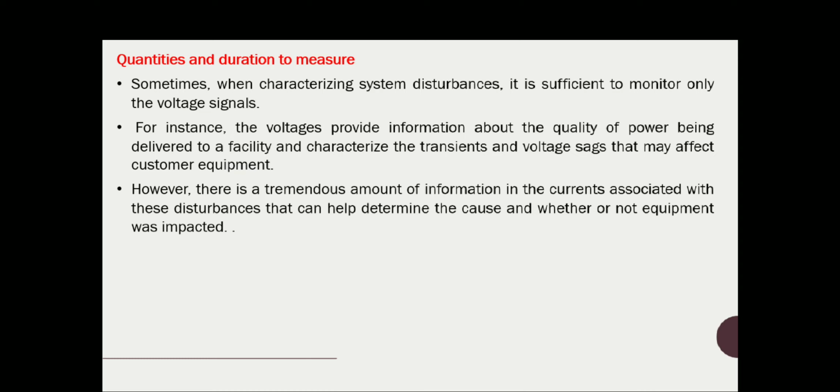Also, current measurements are required if harmonics are a concern, since the current characterizes the harmonic injection from the customers onto the power system.